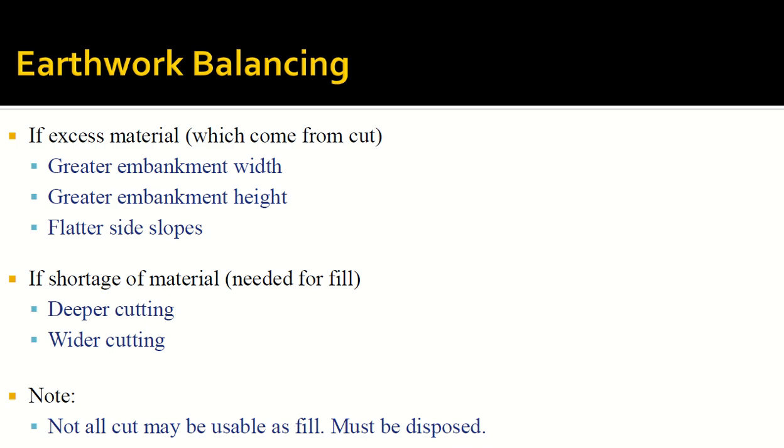Okay. So I need what? I need cut and fill both, right? I need some cut areas and I need some fill areas. If I have only one type of them, I will never balance. If I am only doing cut and cut, I will never balance. I am only doing fill and fill, I will never balance. Okay. So I need to balance between them.